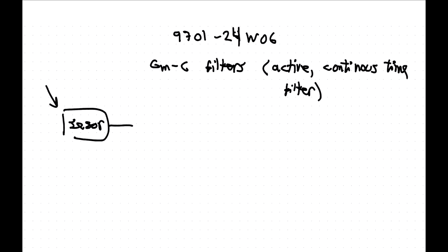What you normally need to do is probably have some kind of amplifier, and then what you want to have over here is an ADC. This is a very typical electronic system, but of course the ADC is typically a discrete-time system, so you've got a sampler somewhere.